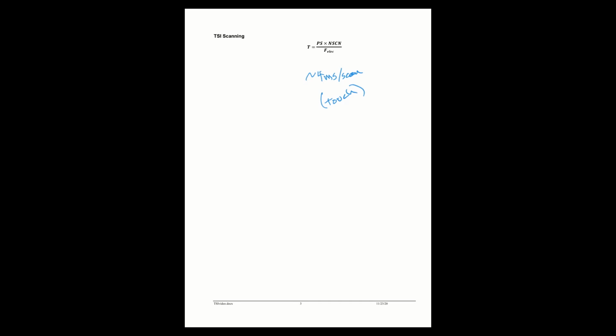The time it takes to scan, because the electrode frequency goes down when you touch it, so the time it takes to scan goes up. So the time it takes to scan the touch sensor depends on whether you're touching it or not. And so this is kind of the worst case.